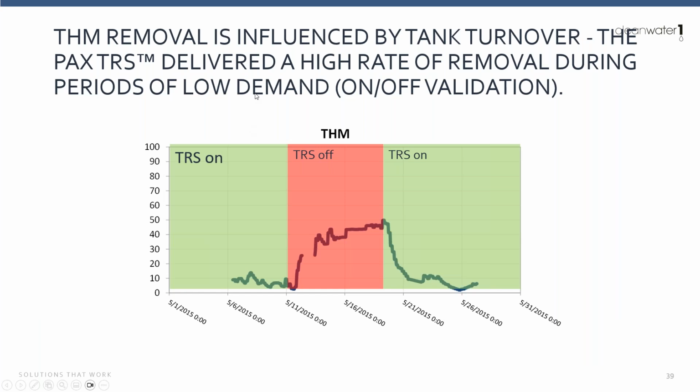These guys had already installed an online THM analyzer, so we're really able to get real-time data. So they're auto sampling once every 4 hours, so that's why we've got so much data here. And you can see, I remember when this came in, just being so thrilled to really see the results. You know, absolutely crushing these THMs. And there was a bunch of backslapping going on.